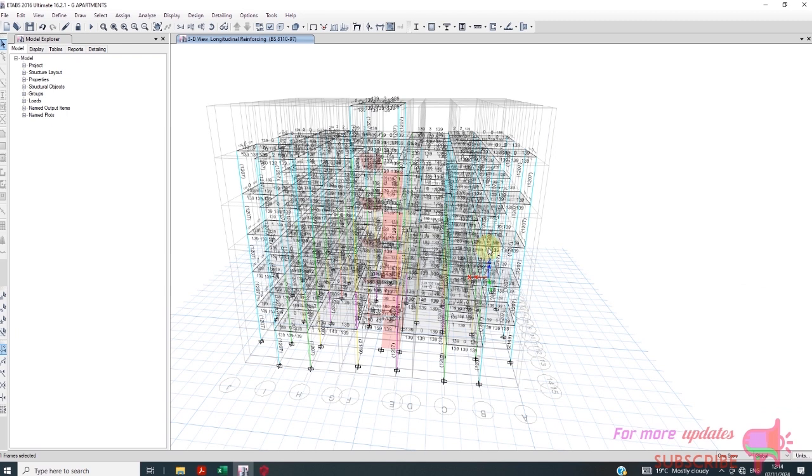Because most of the buildings that you will design are residential, and inputting incorrect load values would mean that you have not designed for the correct load value, and the structure may fail. So to avoid this, you have to make sure that you know the exact or correct value that you should use for extra dead load.